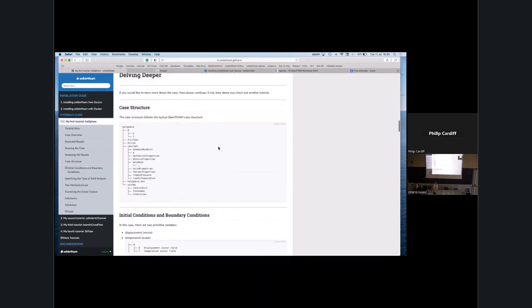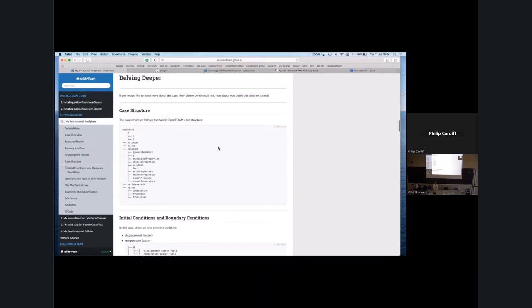So that works, but for the FSI part, there is a branch, maybe a stale pull request, where somebody did port it to use thermal coupling to couple the interface, but I'm not sure of the status of that. It wasn't integrated because there were a lot of changes. So you could definitely do it with preCICE. You could use this solids4foam solver, pick the thermoelastic solid model, thermoelastic mechanical law, and then couple it with preCICE. I think that should work. It's actually a good idea to add a tutorial on that. Maybe that's something we should do.